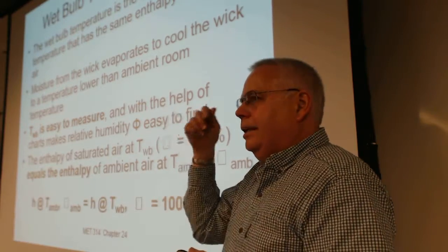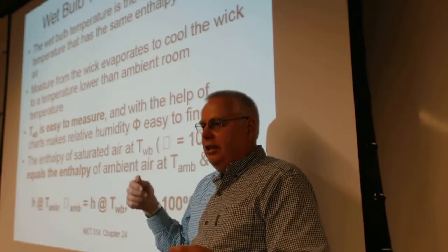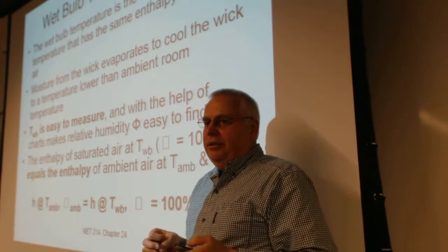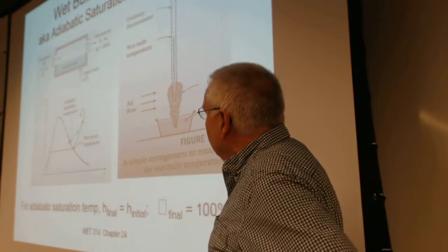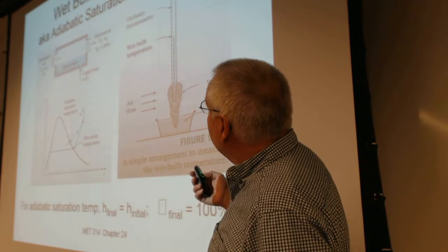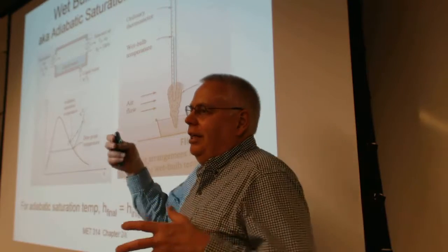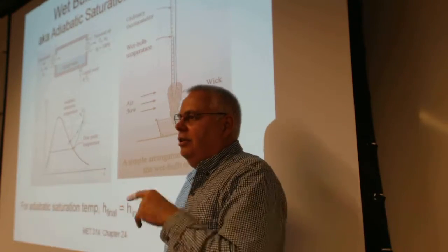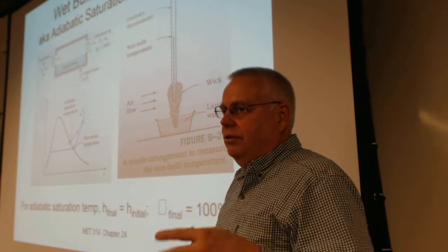So again, my dad used to, when I had a fever, take a wet washcloth and swing it in the air and then put it on my forehead. You can predict that temperature. They all go about adiabatic saturation. Adiabatic, what's that mean? You're not adding energy or taking it away. It just uses energy and converts. Lower temperature, higher humidity. It takes energy to force the vapor up.